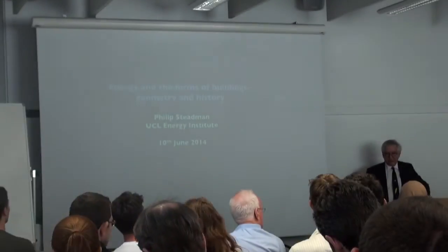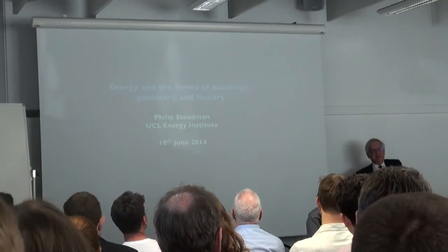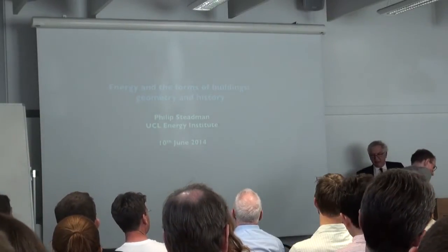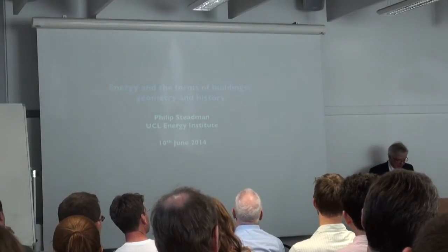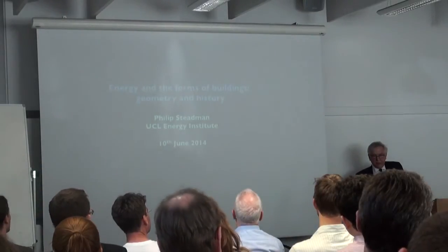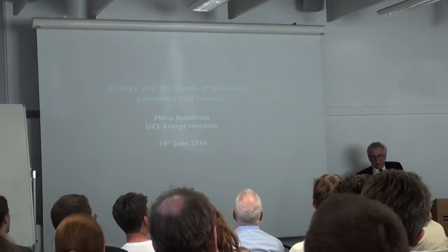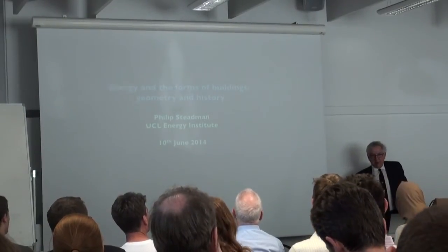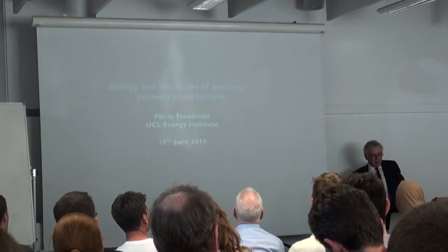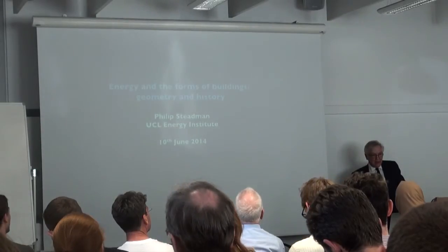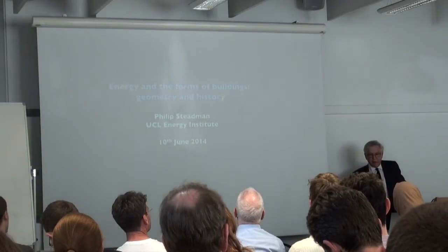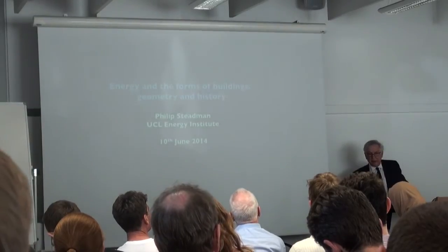Okay, relationship of building form to the use of energy. Of course, the geometry of buildings is not the only factor affecting energy consumption in buildings, and in many cases is only a minor factor. And also, as the insulation of the fabric of buildings is improved, insulation of roofs and walls and glazing, so any relationship between geometry and the use of energy for heating would become weaker. But given the inefficient and leaky state of the stock as it exists, there certainly are strong relationships between geometry of buildings and their uses of energy, which can be demonstrated empirically.